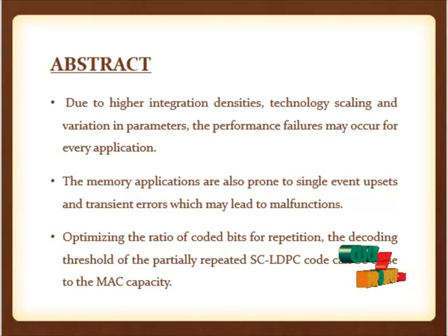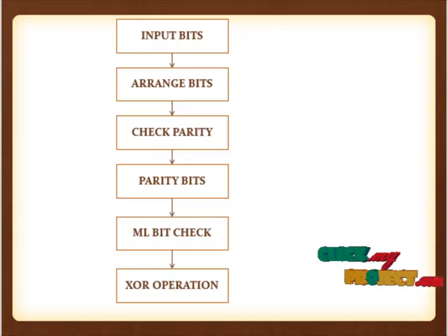In our process, the idea of using repetitions to construct a low rate code is also used to consider the irregular array code, which needs a very complex degree optimization process to design the code for different numbers of users and noise levels. We use SC-LDPC code, which has been used for universal channels. Moreover, another difference of our work is the MAC process. The reason is that during the iterative decoding process, the reliability of messages at the two ends with low degree check nodes is higher than at the middle positions. The advantage is the independent interleavers at each position, so that reliable messages reach the position for convergence. Let us see our process flow diagram.